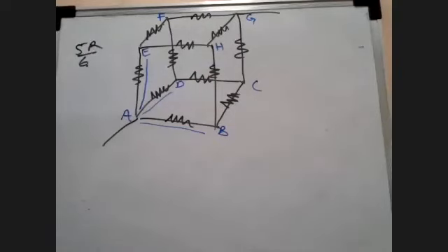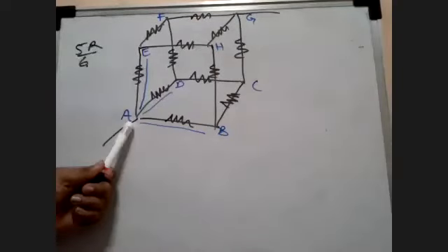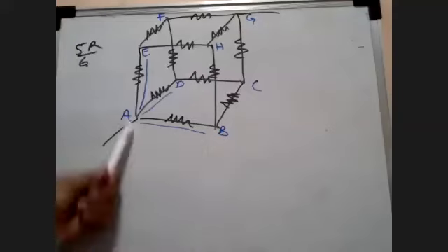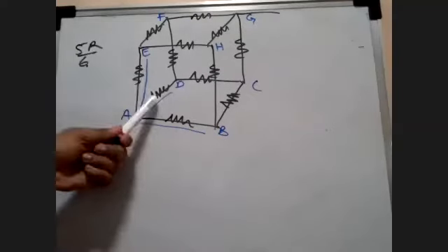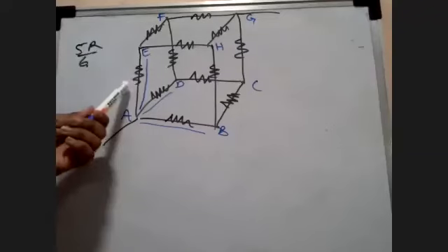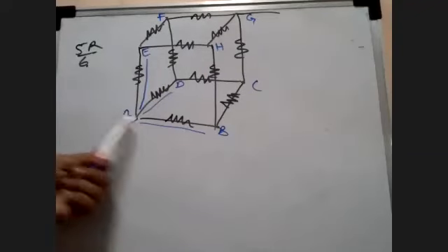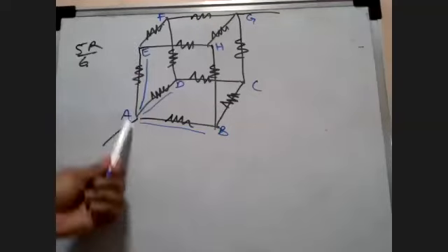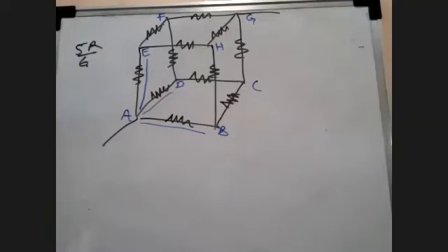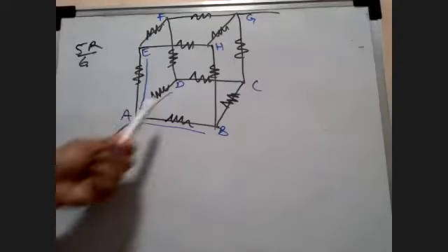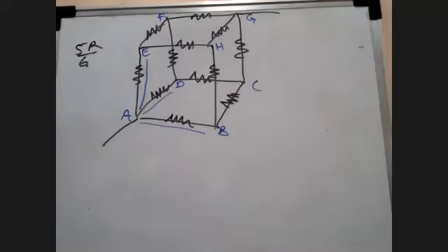Why do you call them equipotential? Symmetry. Okay, symmetry. But also, can I look at it in this way, that since the first part from A to B, A to D, and A to E all have resistances which are equal in magnitude. Of course, I'm considering it to be equal in magnitude. Can I say that these are equipotential? Can I give that result? So in that way, I can say that this point E, D, and B are equipotential.